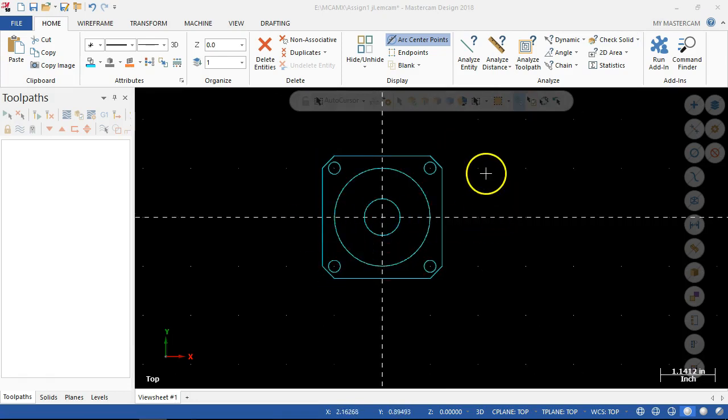All right, so XYZ coordinates: quadrant 1, X positive, Y positive; quadrant 2, X negative, Y positive; quadrant 3, X negative, Y negative; quadrant 4, X positive, Y negative. If for no other reason, that fixed jaw provides a stationary datum. My work stop on the left or the right. Realistically, unless we turn the vise around or you've got one of those double acting vises, and that's a whole other conversation, by the way.